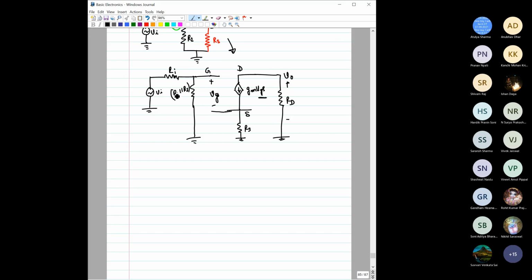Now, if this small signal equivalent circuit is right, then you see, this is the voltage VGS, which is dropping between this and this. So consider it as a battery, and the voltage drop between this point and this is VGS plus the drop across this RS, right?